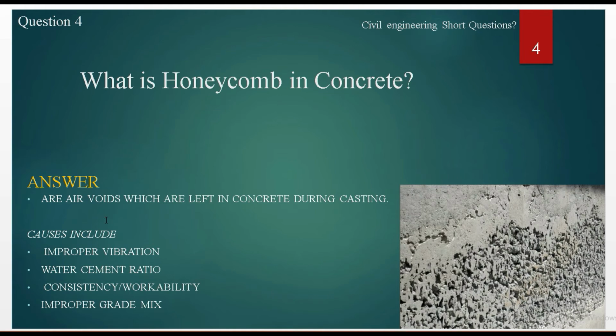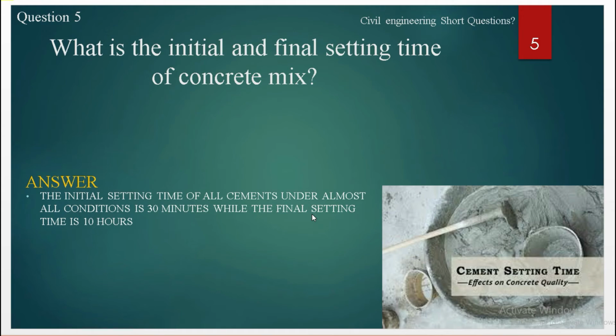So you should make sure that the batch has enough water and it's properly mixed in the mixer and it's properly vibrated during the casting process. That's honeycombs.